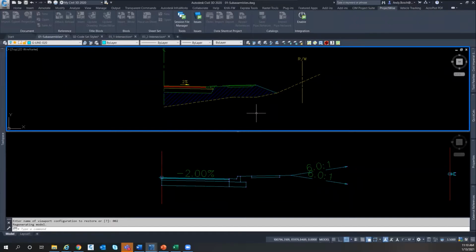You won't know what the cross slopes are. You don't know what the curb style is. You don't know the depths on any of the given pavement sections. You might not know that right away, but it's good to start having this discussion so you can start building your assemblies the proper way at the beginning, rather than trying to redo it towards the end when it gets harder to introduce different assemblies into the equation. So at the top is my defined typical section that hopefully I've gotten by with my engineer.